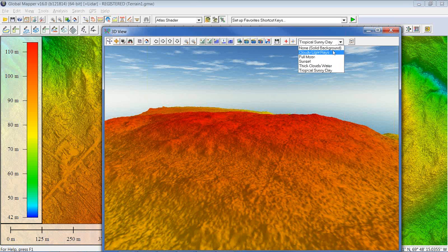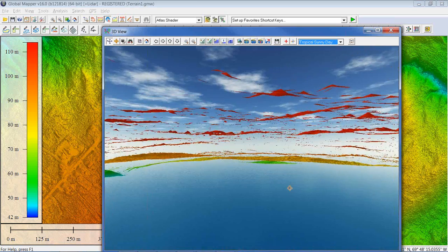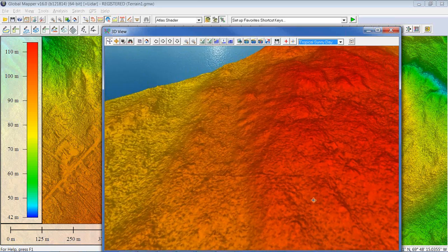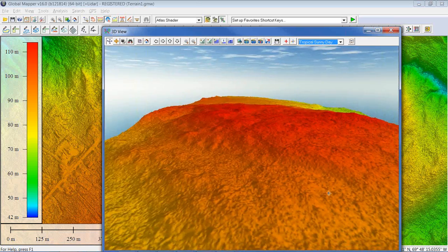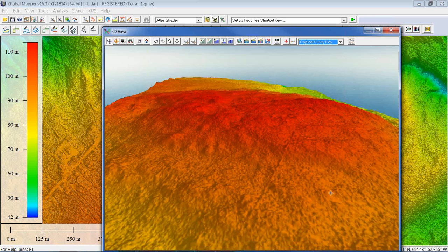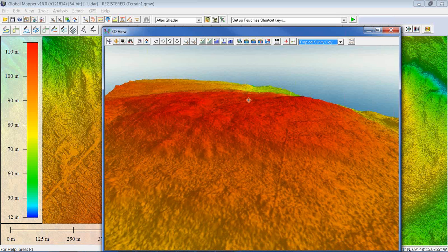We can change that. We have different options as far as the background is concerned. The terrain, as you'll notice, I'm moving around on the terrain simply by moving my cursor. It focuses on a particular point and allows me to adjust the perspective at that point, both in terms of pitch and in terms of rotational angle. Excuse my shaking cursor here, but we can change that view. We can change the exaggeration. If your terrain is relatively flat and you want to accentuate the elevation changes, there's a toggle in the toolbar that lets me emphasize the height or decrease that if necessary. So two options in there for essentially creating mountains out of molehills, as they say.